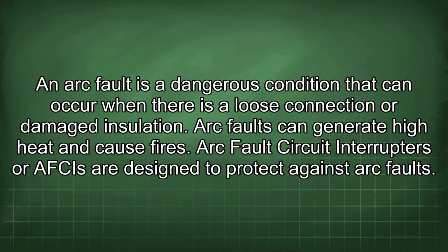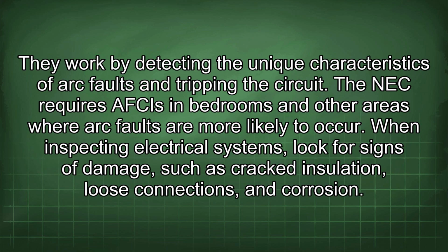Arc fault circuit interrupters, or AFCIs, are designed to protect against arc faults. They work by detecting the unique characteristics of arc faults and tripping the circuit. The NEC requires AFCIs in bedrooms and other areas where arc faults are more likely to occur.